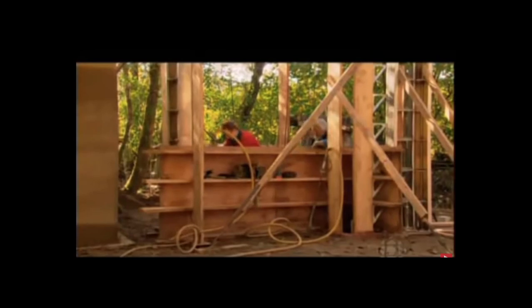The rammed earth walls are tested for strength, and the results indicate that they will be standing for a long time. We take a diamond drill and drill out a cylinder like this, which goes to the geotechnical lab and then gets crushed. And that's how they determine the strength of our walls. And normally the results are twice what the engineer expects. So our walls are extremely strong. How do we know it just won't wash away with a lot of erosion? Well, let me show you. Water does not penetrate a rammed earth wall, so it leads to healthier indoor air quality.